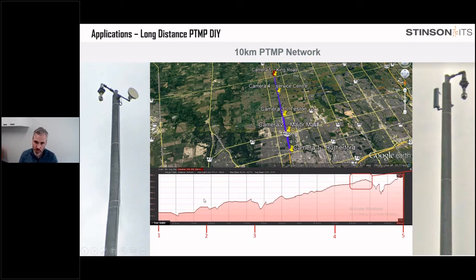This is Google Earth, by the way, and this is the elevation profile tool. I created this blue line, then right-clicked it and said show elevation profile, and you can see here there are no major humps between the start and end point. There was a little bit of one here, so I highlighted that, zoomed in, and saw there weren't any trees there, so it should be fine. But just as there are these big valleys you see here, there could have been a big hill in the opposite direction, which would have caused problems.